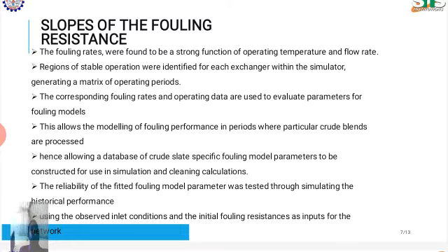Next is the fouling rate on the process side. The vacuum residue stream is known in refinery cases to foul the exchanger. The fouling by the stream has not been visually confirmed, but we have to acknowledge this possibility based on past refinery experience.